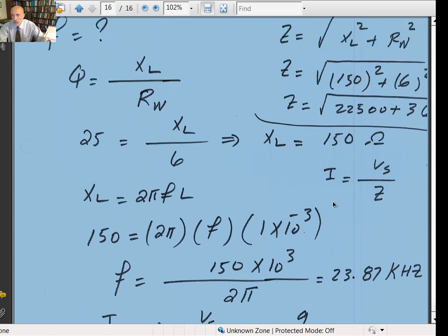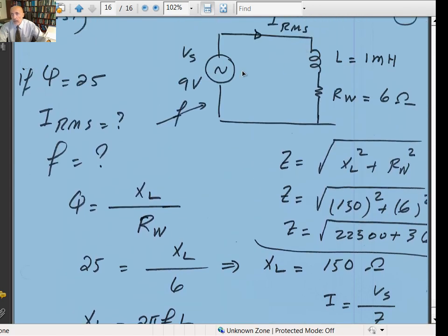Every time you have an AC circuit, the inductance will have a voltage across it, and the resistance will have a voltage across it, but they're not in phase. They're 90 degrees out of phase. And that's where it gets a little bit complex when you're dealing with AC circuits. With DC, it was just clear cut; you just do the calculations. But with AC, you cannot combine the inductive reactance with the resistance directly. They're out of phase, and that's why they do phasor calculations, which we'll discuss in the next chapter.